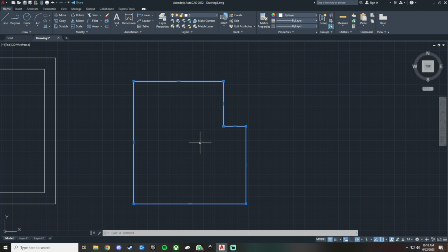And you now want to work on this project again because the client has come back to change something. And you don't want to work on this entire item, you only want to work on parts of the item. But now you've drawn this in polyline, so instead of drawing it again, we can now explode it. So what we're going to do is select this object, and click explode. And now you'll notice that each of the items or lines are now on their own and no longer linked.